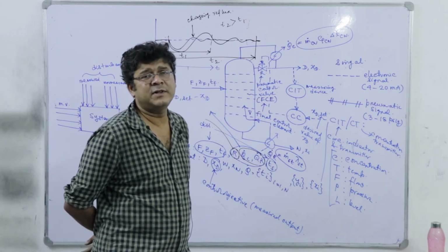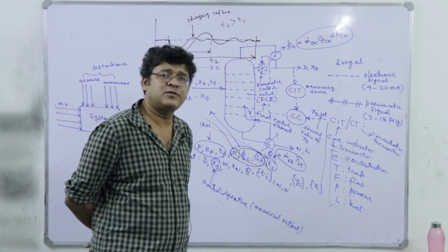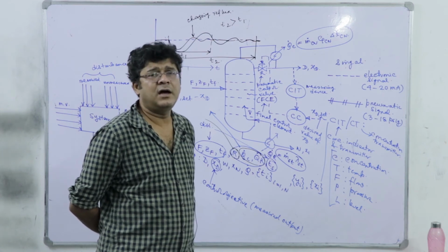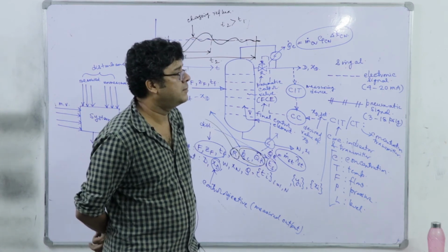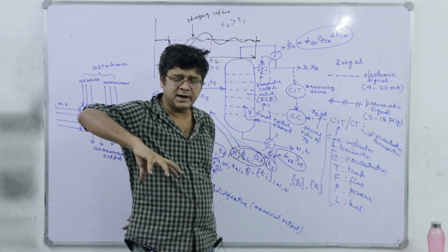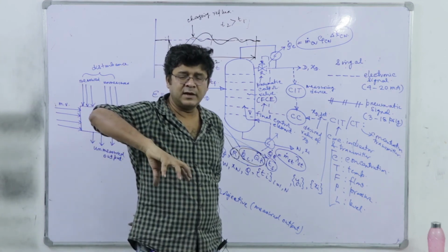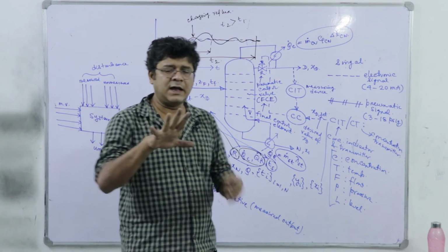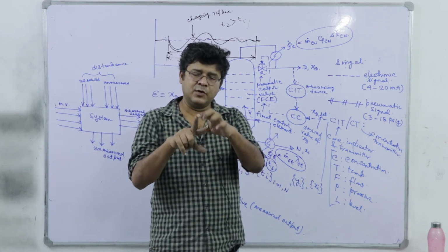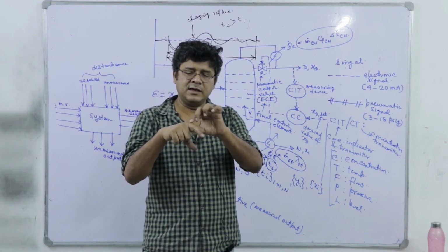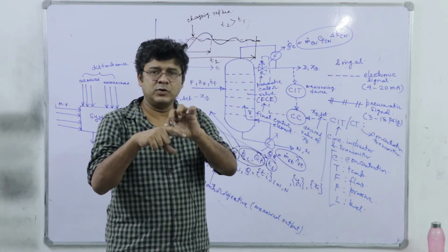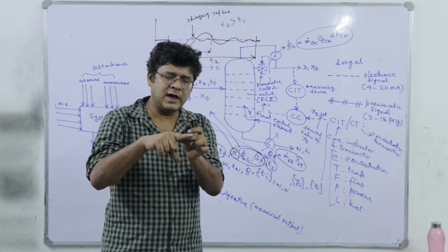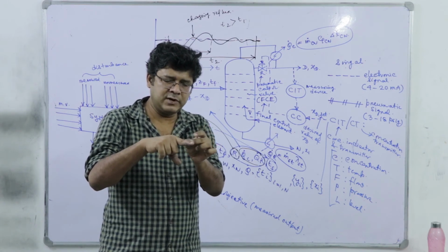So what are the other examples of this final control element? It may be a switch, it may be a relay, it may be a solenoid valve, it may be a stepper motor which will rotate in a specific direction by some degree, and those are specifically used in robotics. Like a robot arm, think that I am trying to replicate the motion of this finger. So here, here and here at these three joints we have three stepper motors and we have to touch something. So what can we do? There will be coordinated, synchronized rotations between these three stepper motors.